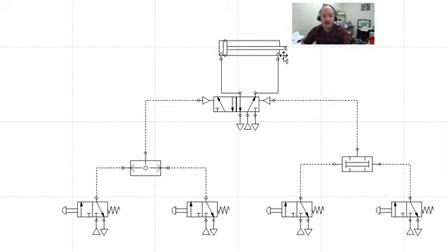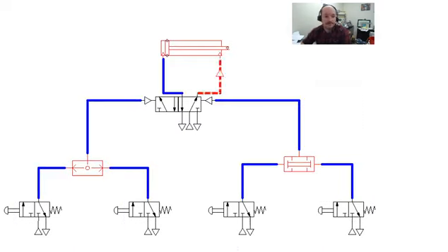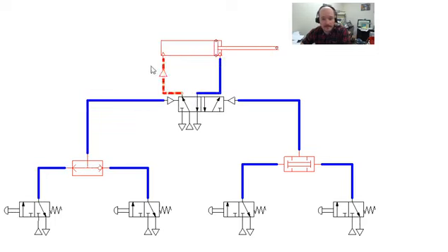So there's enough of me walking you through it. Let's go ahead and take a look. So I'm going to activate this push button. That extends the cylinder out. Now notice this went red. This is sometimes referred to as a specialty check valve. That shifted up over to here and shifted the directional control valve into its position that allows the cylinder to extend.